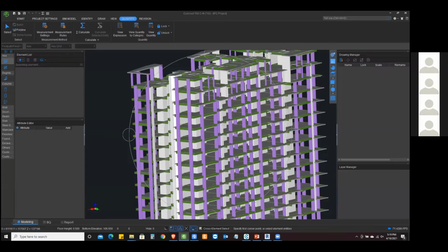And along with that, you have the BIM model with different levels of detail or information. You have LOD 100, and then 200 and 400, as you mentioned. So you can basically utilize any of these models at any stage of your project. Now, if you're not a QS, you would necessarily think that if I have a complete model, then I may perform the calculation, but that's not the case. At every stage, you have to have calculation side by side of the quantities. So along with your model development with different LODs, you are updating the model and getting the quantities done.